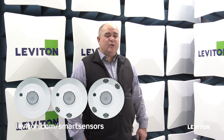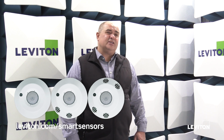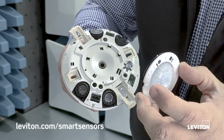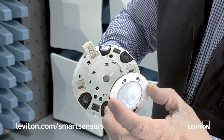In addition to that, we have the UL 924 listing within this device, which is a tremendous feature all in one package. And then we also have single and dual relay models, including 2 interchangeable lenses and aisle masks. And those interchangeable lenses make it able to be used in rooms that are either 8 to 12 feet, or simply by changing the lens, going from 12 to 20 feet.